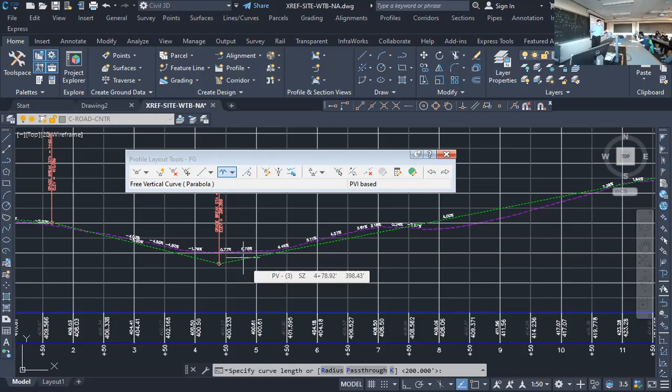For the most part, I don't think you're going to have a case where you're going to make a curve anything other than 200 feet. If it's like a short curve like this one you can make it 100, but anything like that, you can make 200. Now there's ways to do these based on sight distance, but for right now, do something uniform. 200 is a good start.